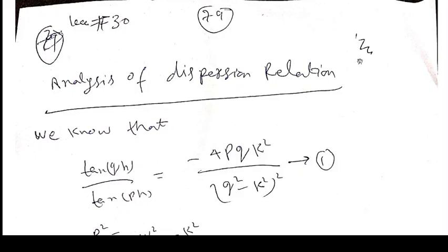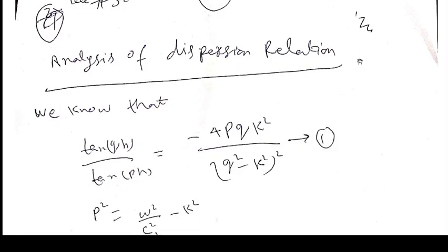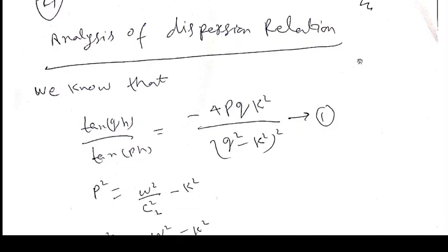Today we will see some analytical proofs that when CR is less than CT, then we have only one mode which approaches the Rayleigh wave speed CR, and infinitely many modes intersect the line CL, and we have infinitely many modes between CL and CT.